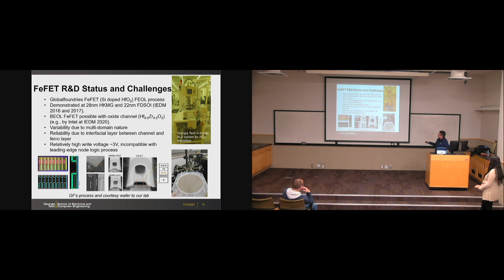This is the same value proposition for RRAM and MRAM actually. But for the FeFET, for example Intel, their position is different. They want to use ferroelectrics not only in the FeFET but also in 1T1C FeRAM. They want to use it for last level cache, so they want to have an eDRAM kind of application. They have a group working on that. And there the engineering target is different.